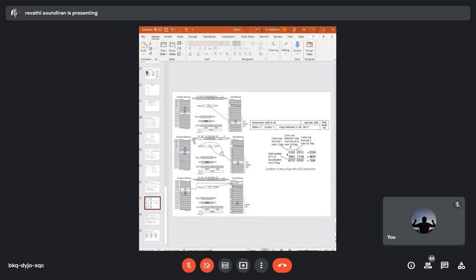When you perform the addition over here, in the third bit, 1 plus 1 is again 10. So you have an auxiliary carry. So when you perform the 3-bit addition, you have a carry out, which is taken out. So the carry out of your bit 3 sets your auxiliary carry also. Okay, so now your auxiliary carry flag is also set.